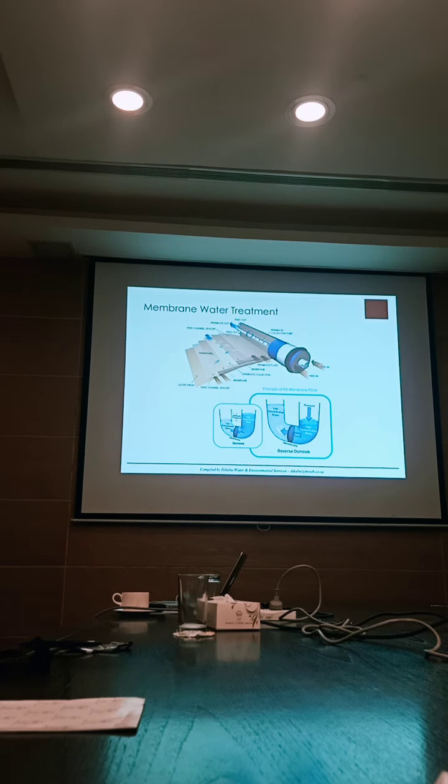So taking a brine solution and putting it through a membrane. Brine treatment, we'll talk about it just now, is starting to use forward osmosis or regular osmosis as we know it. Remember reverse osmosis, we're putting pressure on the membrane and we're pushing the material through it. Regular osmosis is relying on a high concentration, low concentration interaction, the movement of salts through a membrane.